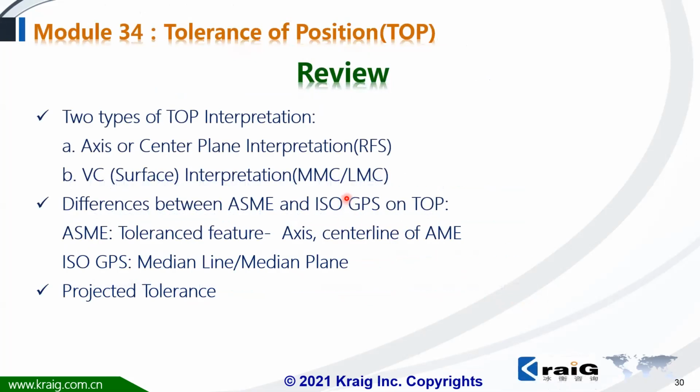All right, let's have a quick review of this module. In this module, we have learned about TOP. We have two interpretations: either the axis or center plane interpretation without any MMC or LMC modifier, or the surface interpretation or virtual condition boundary interpretation if there's MMC or LMC.